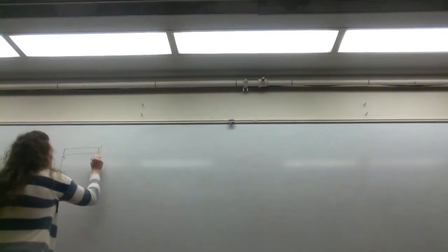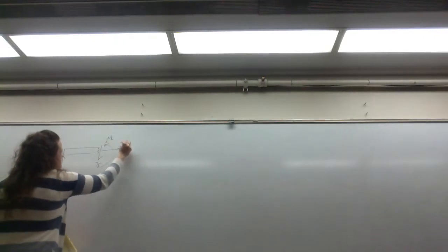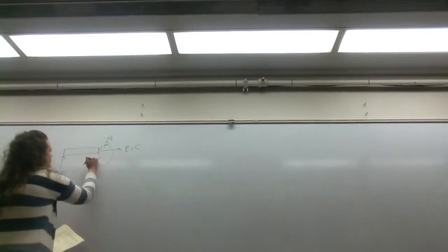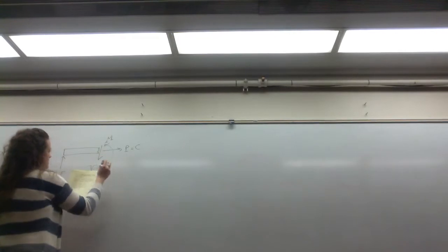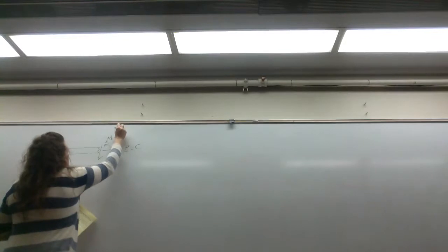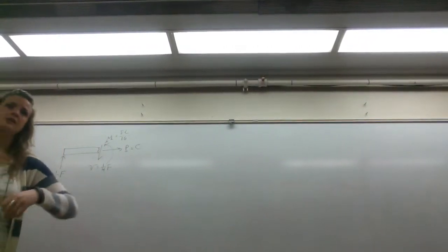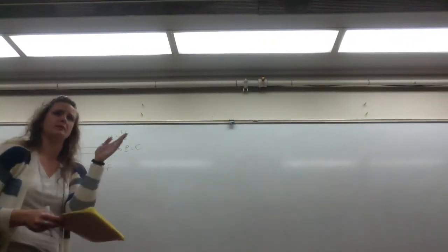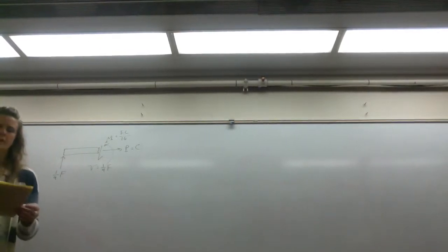And we applied our internal forces with a positive sign convention. We found that our shear force was equivalent to 1/4 F, the same as our reaction force, and our moment to be FL over 16. This was at a very discrete point, at point C, where we applied our equations of equilibrium after we demonstrated our internal forces with the correct sign convention.